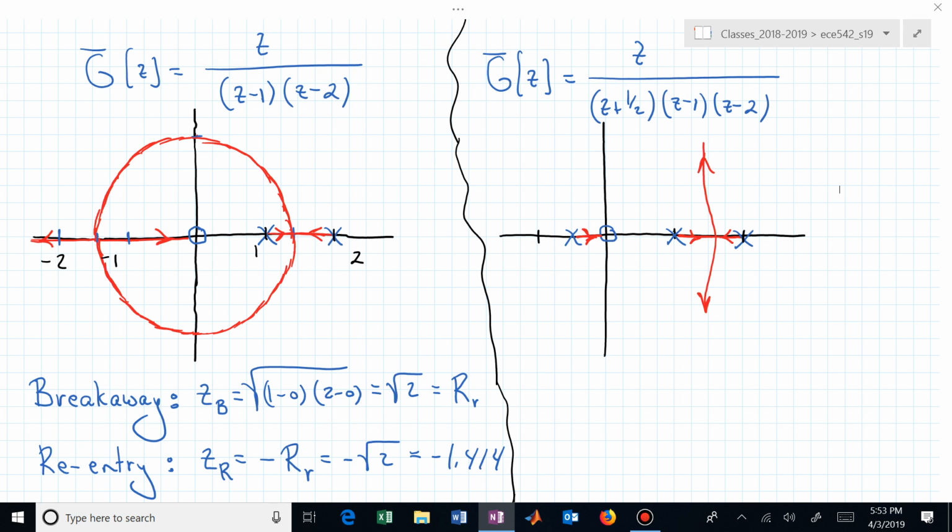In this case, how many pieces of that French bread exist for the pole zero diagram on the left? You have 4 different pieces. I might want one of those pieces more than another, but so be it. We now have 4 pieces of French bread. We have to figure out which of those 4 pieces actually belong to the root locus, which will be colored red.